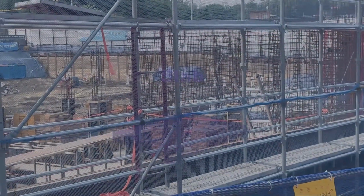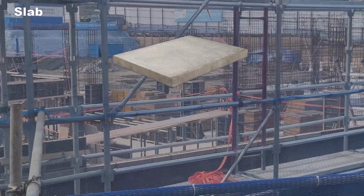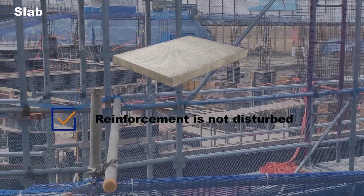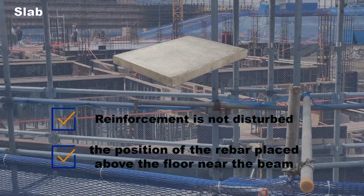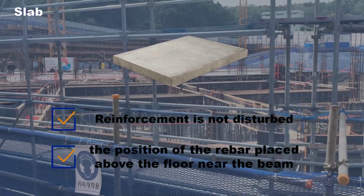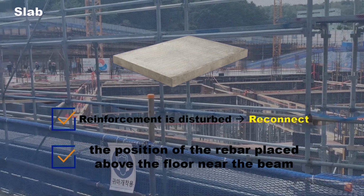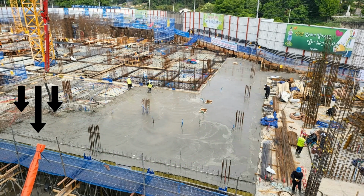Lastly, slab. When pouring the slab, care must be taken to ensure that the reinforcing bars are not disturbed, especially the position of the reinforcing bars placed above the beam. If they have moved, they must be reconnected. Also, concentrated concrete pouring in one area should be avoided.